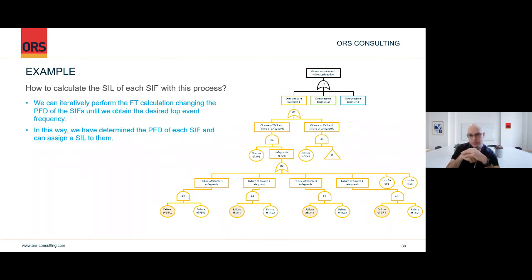There are some explanations as well in some Norwegian NORSOK documents, so you may want to go through those. NORSOK has some guidelines on what frequency is acceptable for some overpressure events in some segments of offshore plants, for example, offshore platforms. And for money, for example, acceptability for money, it's up to the organization to decide. Regulators normally don't have a view on that, so that's up to the organization.